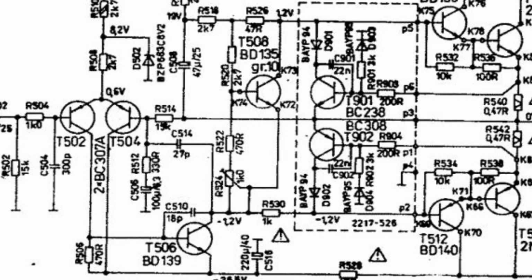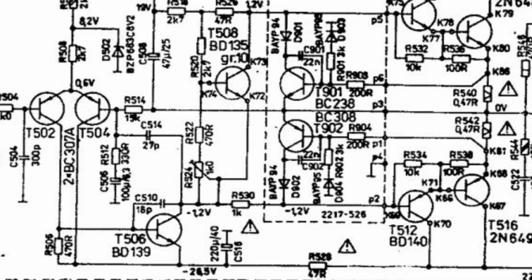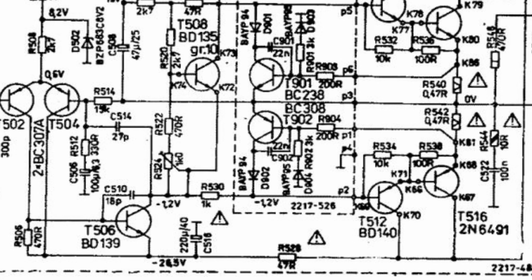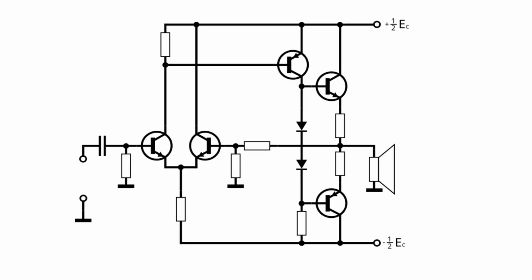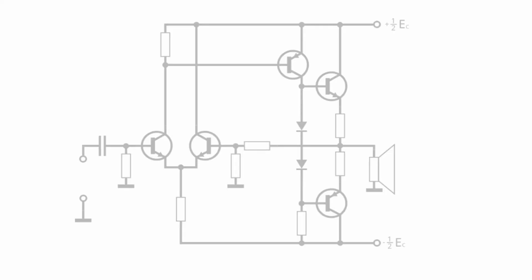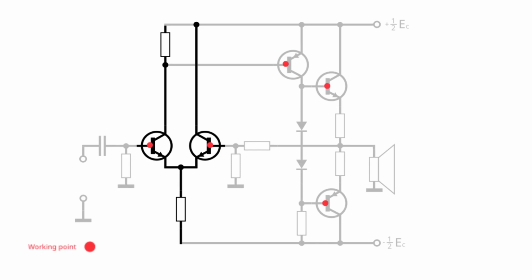Power amplifiers have many applications. We will discuss here only an electroacoustic power amplifier, as it has all features of a typical power amplifier. A typical power amplifier is made of three stages: differential amplifier stage, voltage amplifier, and current amplifier. The differential amplifier stage is the first stage of the power amplifier. It compares two signals, the input one and the output one. But the most important job of this stage is to automatically set the working points of the transistors in the amplifier.